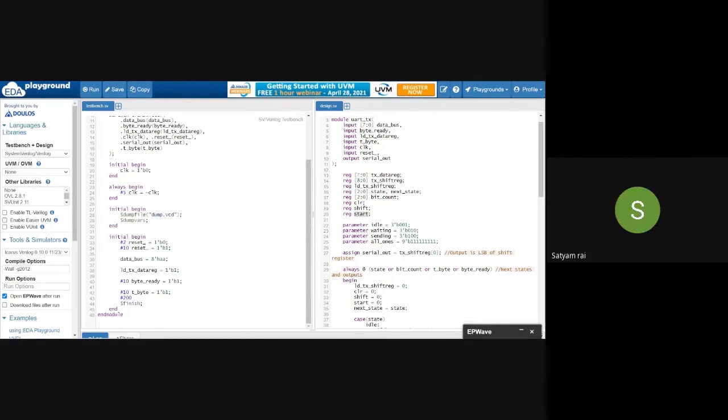See, that's my point. Inputs are only these. These are the things which, remember I told you, there's a host and there's a modem. Host controls these things. It doesn't control the data bus. These signals are what are controlled by the clock. The clock is clocking these four: byte ready, load data reg, clock, and reset. These are the only things which host can do.